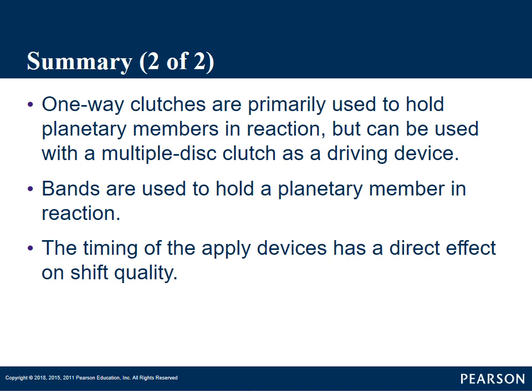After this section, we're going to get into transmission electronics and how to diagnose transmissions. Diagnostics between how it shifts, determining whether something's slipping or maybe shifting too hard. When we talk about electronics, we're getting the scanner out, making sure all our electrical solenoids and speed sensors are operating correctly.